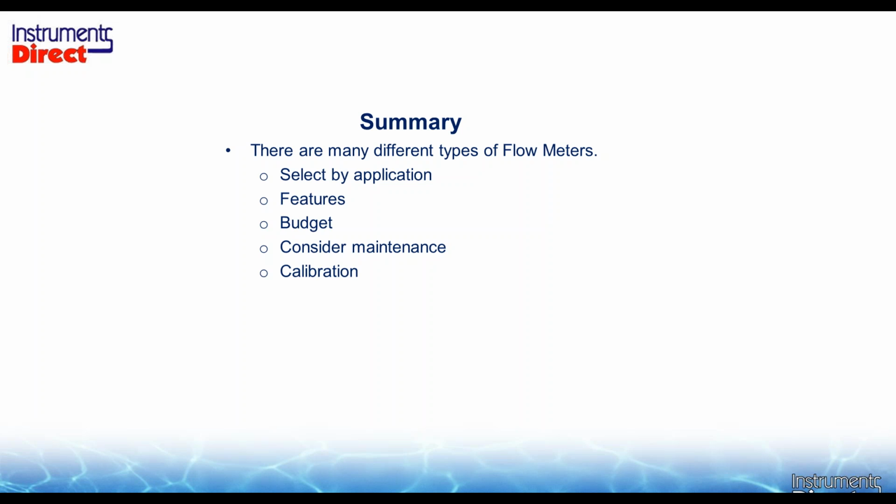There are inline devices, high-tech devices, and non-contact devices, and they all depend on your budget. If you want an ultrasonic flow meter, you can get a dedicated one for around $2,300. You can get an inline water meter for 2 inches for $800 or $900, but you've got to cut pipe and install it. These are decisions you need to make.